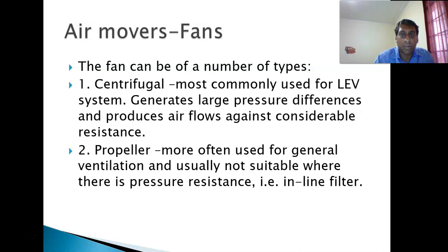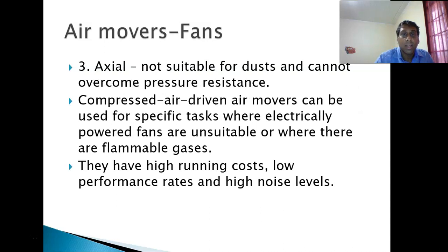You have actually seen that one, and this one here, axial, not suitable for dust and cannot overcome pressure resistance. Compressed air driven air movers can be used for specific tasks where electrically powered fans are unsuitable or where they are flammable. Running costs, low performance rates, and high noise levels. I can't remember that. I know they had asked about 2 types of fans for the LEV system. So I think coming out of that, I would have done this slide, centrifugal and axial, and maybe some of the advantages and disadvantages of them anyway.